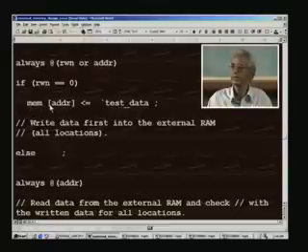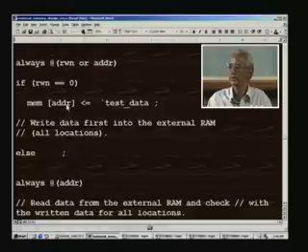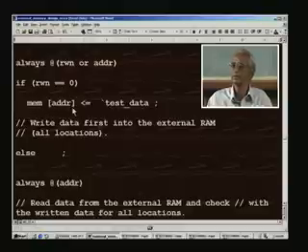This reg mem we have seen to be within the test bench, and to start with the address will be 0, and that is what we have seen while looking into the address, initialized to 0 at the power on reset. So, it starts with a 0 and automatically the design increments the address, and also applies a read or write pulse only once in 2 clock cycles. So, automatically the design takes care of writing into this RAM, although this external RAM is within the test bench here,